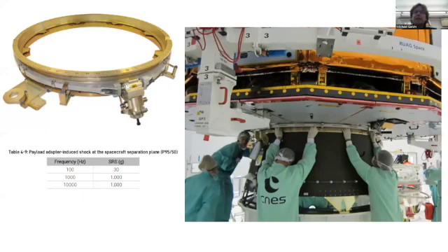But there's a variety of high shock release mechanisms involved in these clamp bands. And these days there's some low shock release mechanisms as well. But again, on a typical launch, this is often a high shock event, releasing this clamp band and releasing the spacecraft into a free flying orbit.